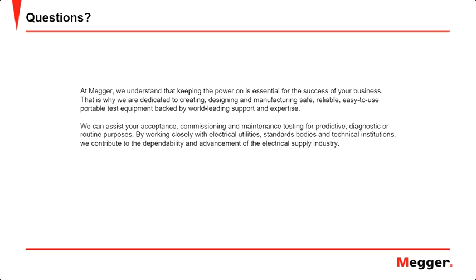And given that you have that kind of access to the cable as well, if it's underground and direct buried, how would you put HFCTs on that specific cable, right? So that all comes down to the logistics of it, and sometimes it becomes much more expensive such that you can't really go towards an online monitoring system, and you have to resort to an offline monitoring system.